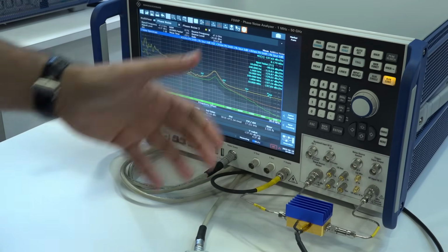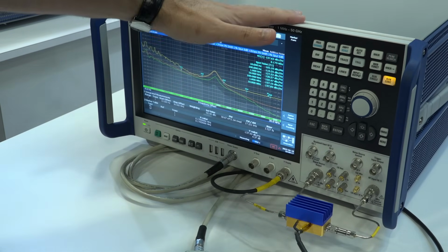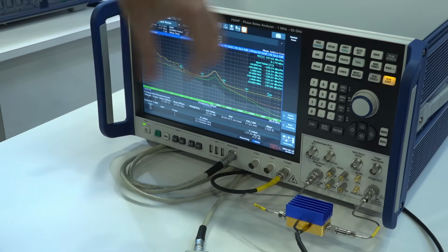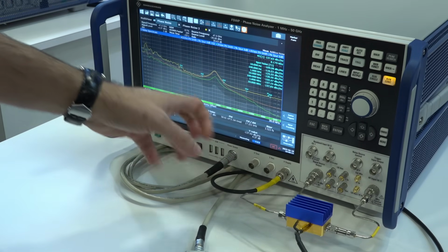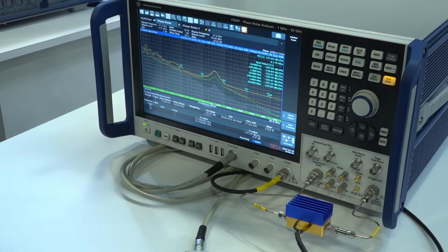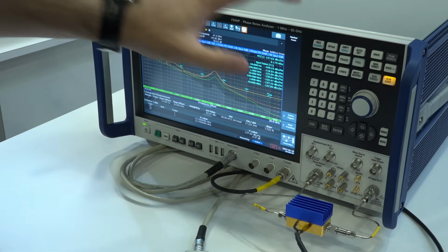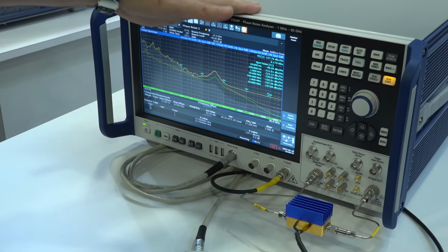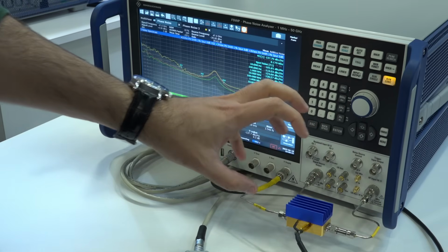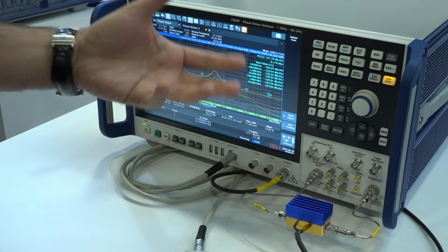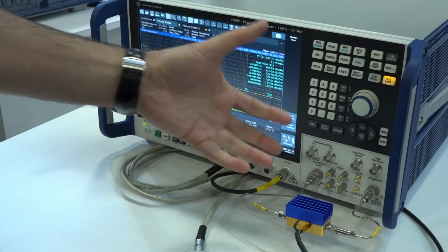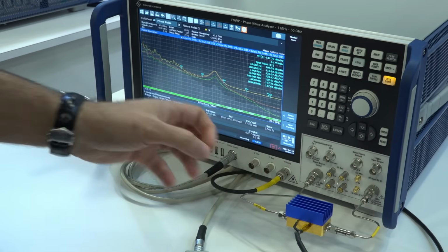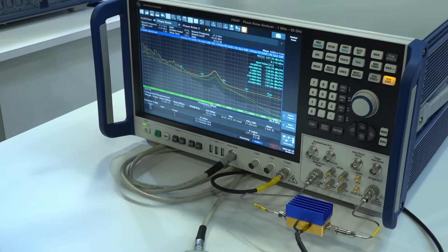And that combination now gives you a huge dynamic range of phase noise and additive phase noise capability all in the same box. Now, naturally, there is obviously supply and control voltages in here for VCO characterization, doing super fast cross-correlation up to 54 gigahertz. All those are the classic features that this FSWP has had. But it's really interesting that once you make an instrument sophisticated and advanced enough in terms of its analytical capabilities, you begin to extract unusual features like noise figure from an amplifier in a completely different way. So it's exciting to see that.